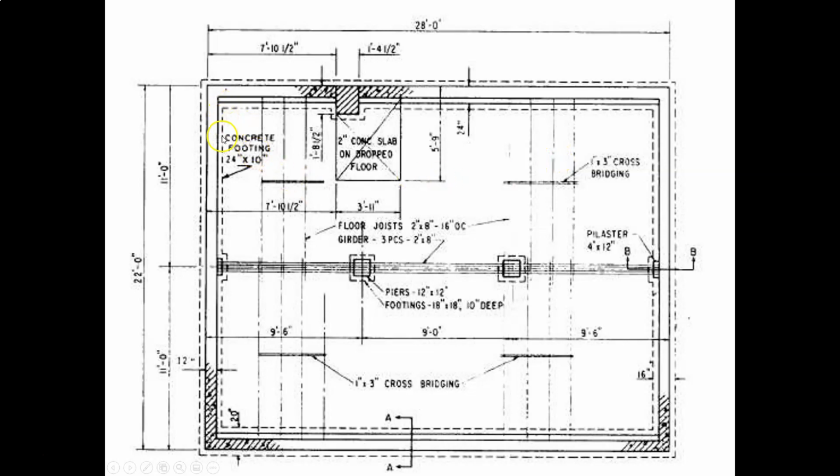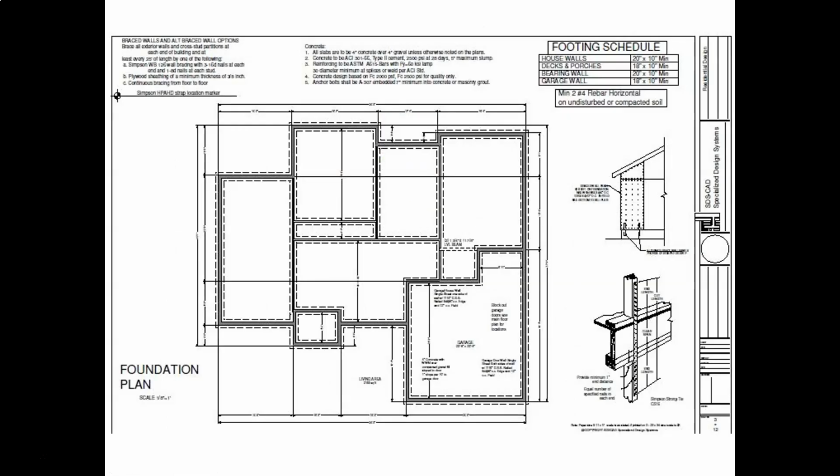And then if we were to do the concrete slab inside this space, we would have to take that 28 feet and pull it in the thickness of the wall, which is a foot. So this 28 would become 27. And then over here, that 27 would be reduced further a foot to 26. Okay, so a lot of maneuvering and acrobatics with the dimensions when it comes to concrete. Okay, this is what a contemporary kind of plan would look like.